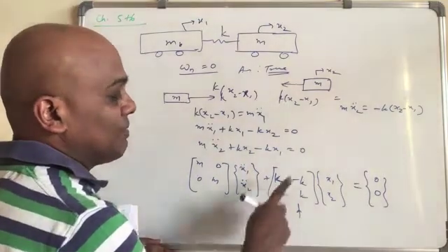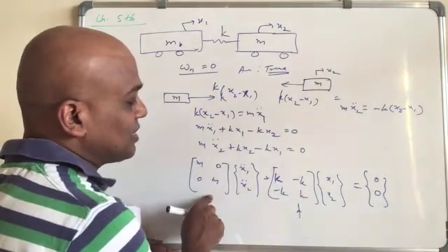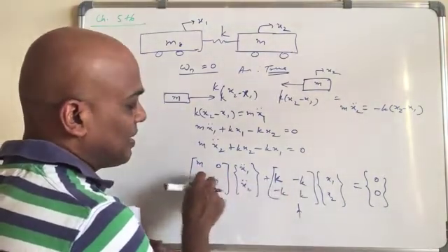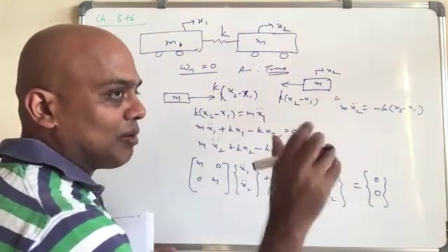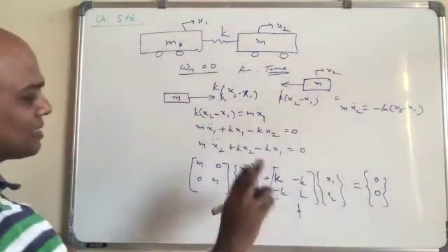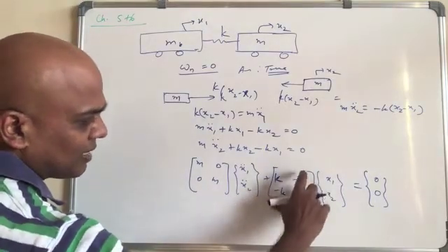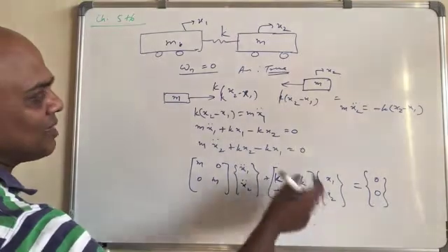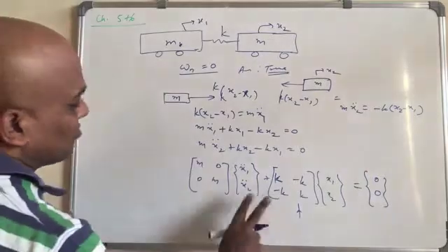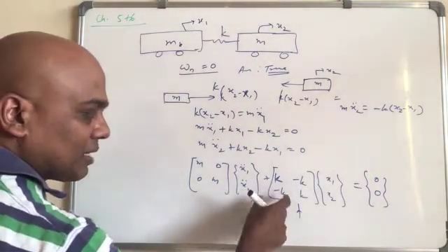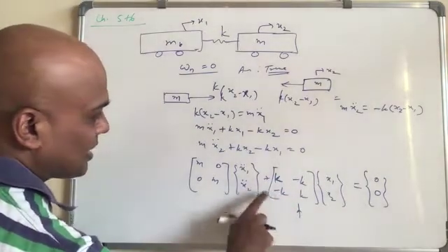Okay, that really means if lambda is equal to 0, then multiplying by m1 will also make it 0, and this matrix minus the 0 matrix will, in that case, be the whole matrix. What I mean to say is that if the determinant of the stiffness matrix is equal to 0, automatically one of the eigenvalues will be 0. Even though I did not tell this in the lecture, you can see it here also. Automatically you will find that it will be the case.